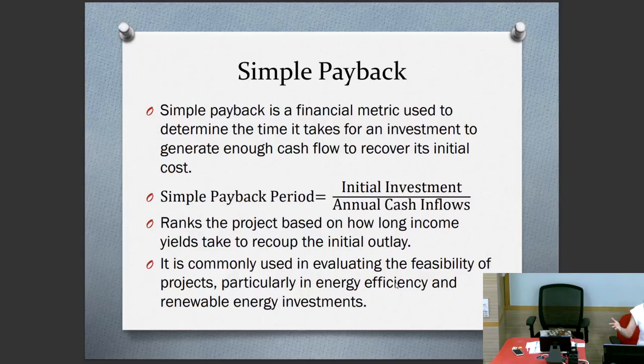So for an energy efficiency program, you can save energy consumption, right? Like the light retrofit, we replace the fluorescent tube by LED, then less power consumption, less energy consumption, and therefore you pay less for the electricity fees. So it will generate some annual savings. The initial investment is the total cost that you need to pay for the light retrofit, and then divided by the annual energy fees saving, then it would be the simple payback period.